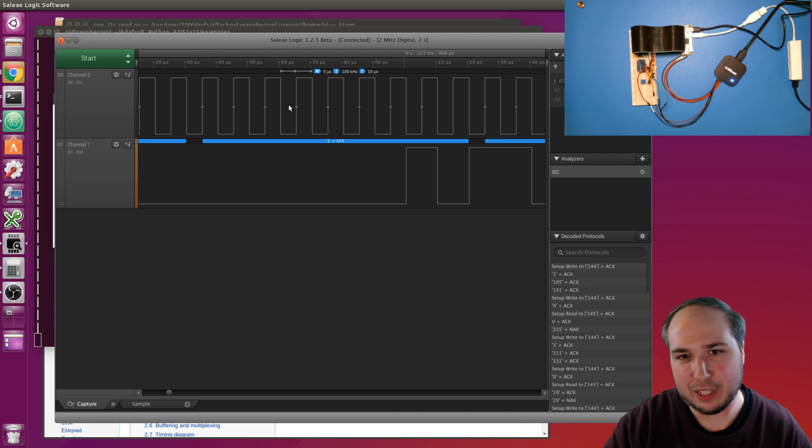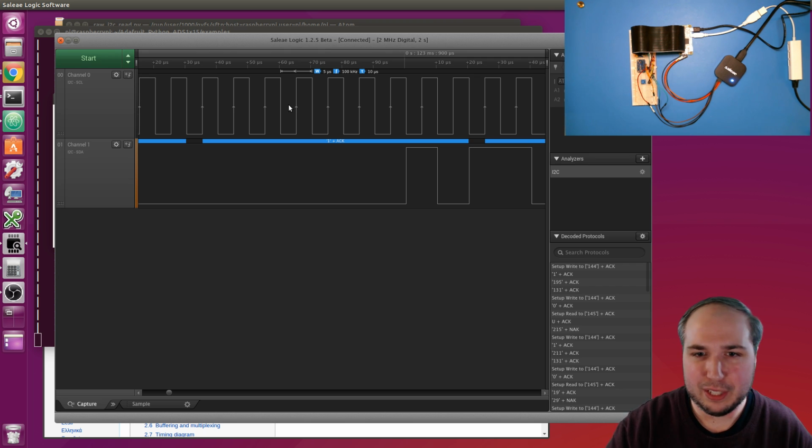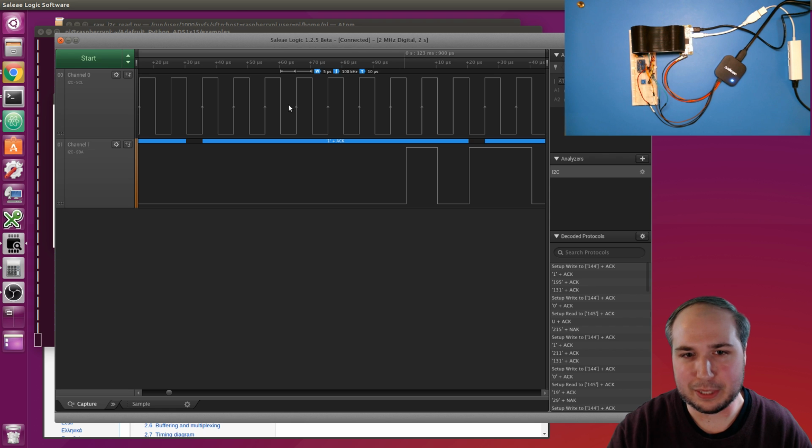This is in contrast to the SPI bus, where you can control the speed as a SPI master. So the Raspberry Pi could run a SPI bus at multiple megahertz. If you have a little LCD display and you want to update it at a fast rate, that's a really good case for using the SPI bus. Versus I2C, which by default does 100 kilohertz. There's a high-speed mode where it can do 400 kilohertz. I think there are even faster modes where you can do a megahertz or more, but most devices that we deal with just run at that default 100 kilohertz rate.